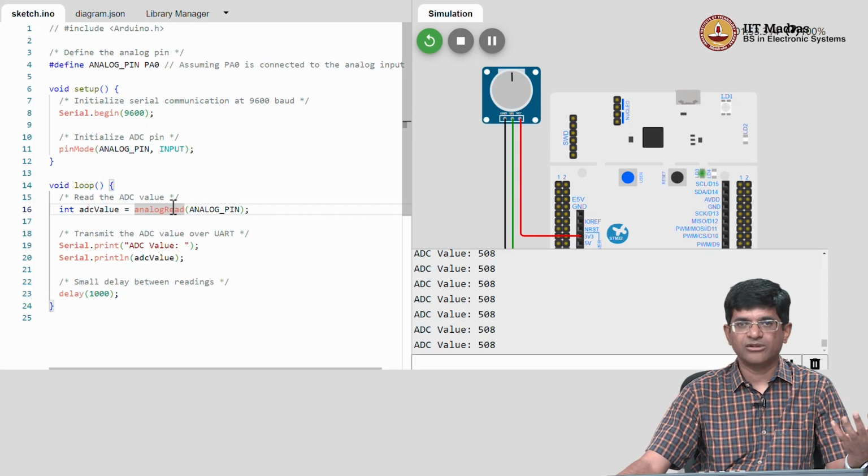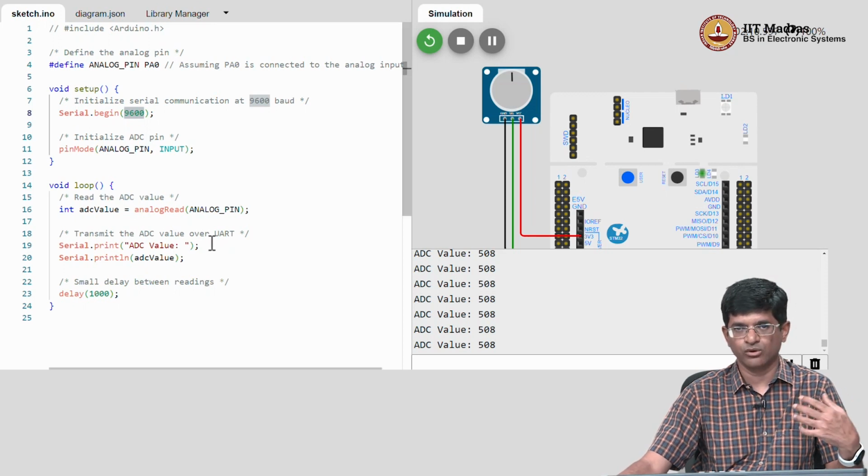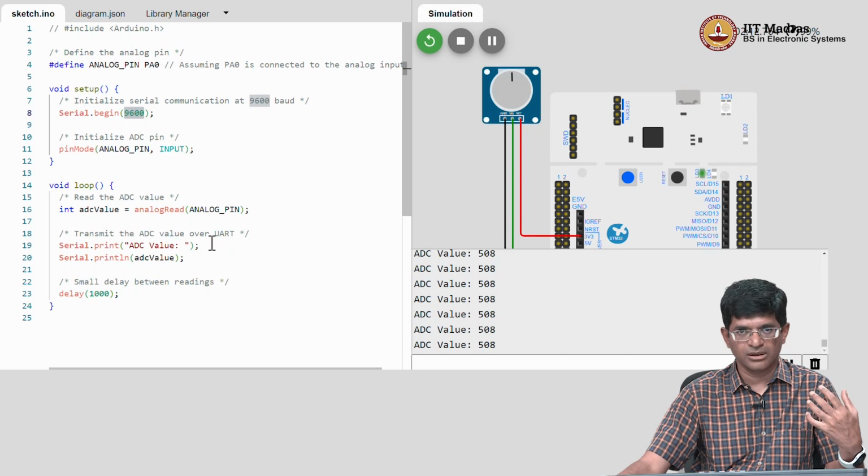It obviously makes your life much easier in terms of how you use it, but it has its own drawbacks if you think about it from the point of view of what level of control you can get. If you wanted, for example, to increase the serial speed, or to change this to 12-bit values, it's not so straightforward to do using this kind of code, and you would find that you need to fall back to the regular C code in order to get that level of control.